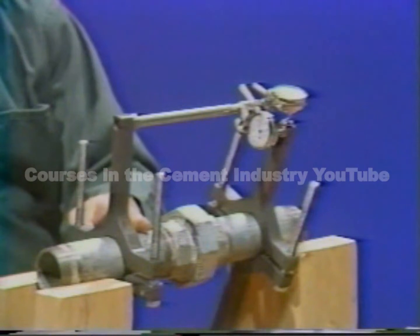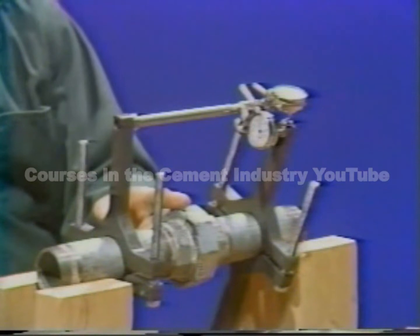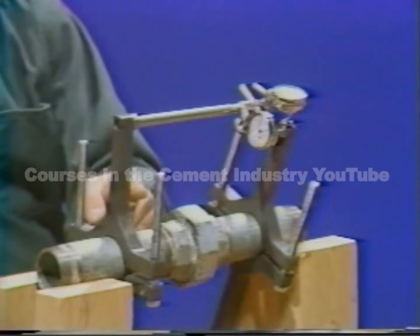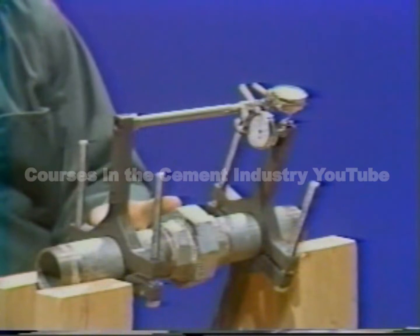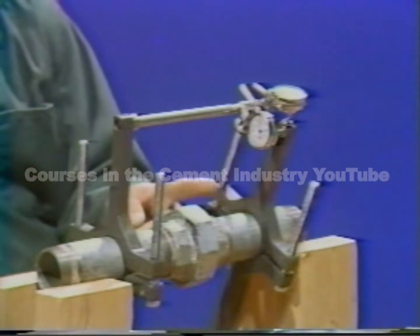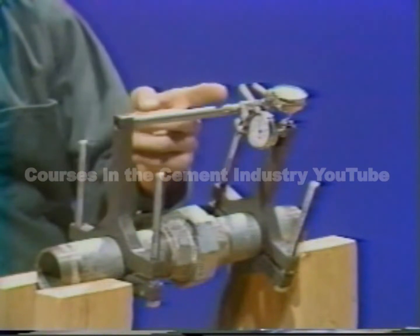So what we have is essentially the same setup we would have if we use the coupling. The only difference is that we're using the post and bracket to reflect shaft misalignment rather than the coupling to detect shaft misalignment. Any changes in the distances between the post and bracket show on these dial indicators attached to the suspended rod.